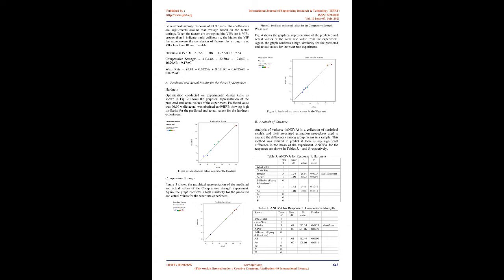B. Palm fruit fiber design formulation. To develop an optimal mix for the sample, a split plot optimal, custom design, which is a specialized form of the response surface method, RSM, was employed. Product attributes are measured as responses from the designed experiment, and they are: Response 1, the hardness, BHN. Response 2, compressive strength, MPa. Response 3, wear rate, J/M3.